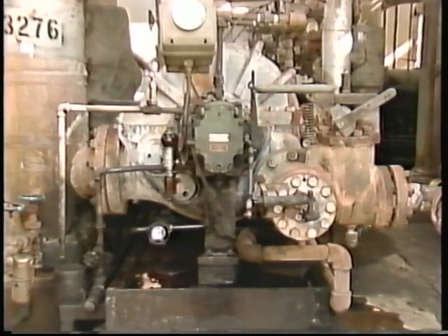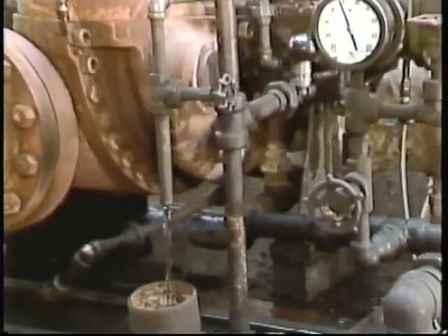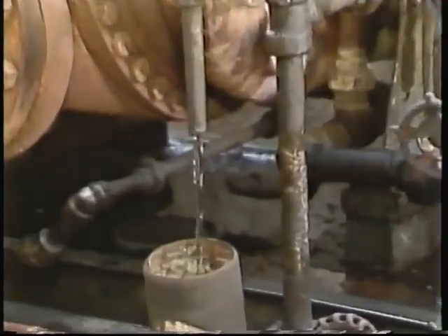For each bearing housing, there's usually a line for water into the jacket. This line may include a valve that can be adjusted. Then another line, also provided with a valve that can be adjusted, routes the water out of the jacket, so the water can be discharged after it has been used to cool the lube oil.